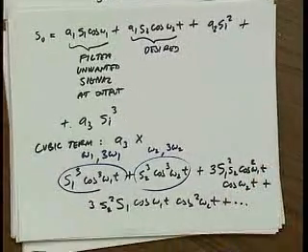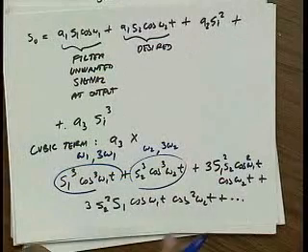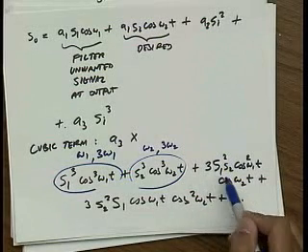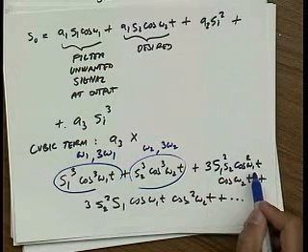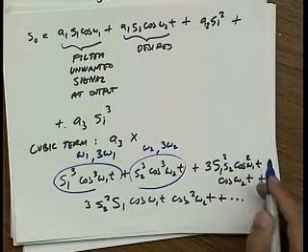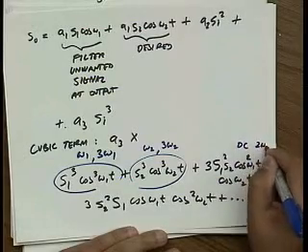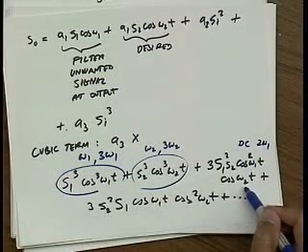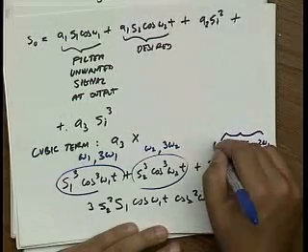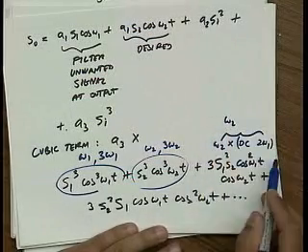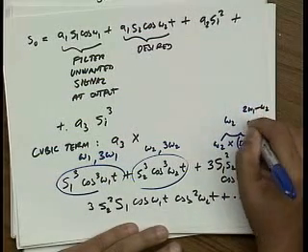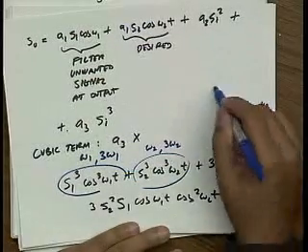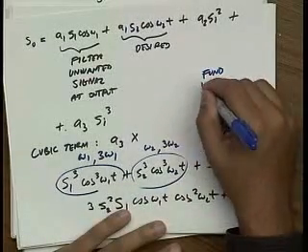All right? Look at this term here. This term is the nasty term. Why is it nasty? Well, remember, S1 is a big number. S1 is that big signal, and I'm squaring it. So it's even bigger now. And here I have cosine squared, which produces a DC term and a 2 omega 1 term. And when I multiply it out by this term, I'm going to get omega 2, and I'm going to get intermodulations 2 omega 1 minus omega 2 and 2 omega 2 minus omega 1. Okay? Well, this is the term that I care about. This is my fundamental. This is the wanted.